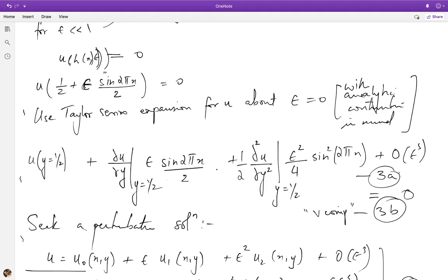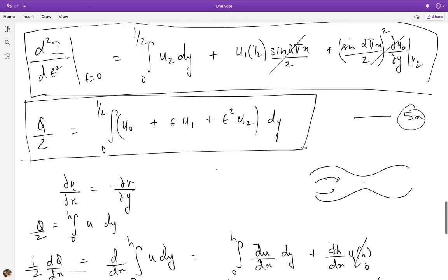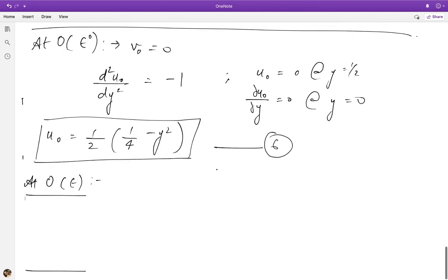And we can then substitute u and v into their corresponding boundary conditions at the wall, at the fictitious wall, or the wall of the base domain y equal to half, and obtain the corresponding non-homogeneous boundary conditions, which is what will actually give us the two-dimensional velocity field. So let us first write out the domain equations.